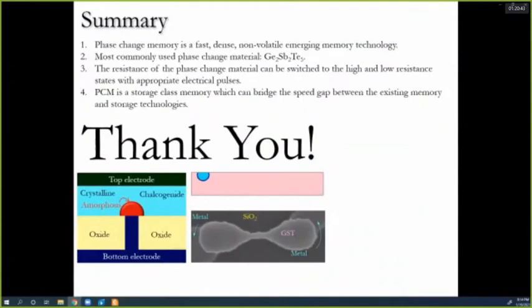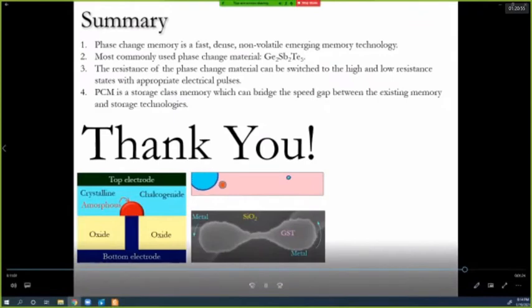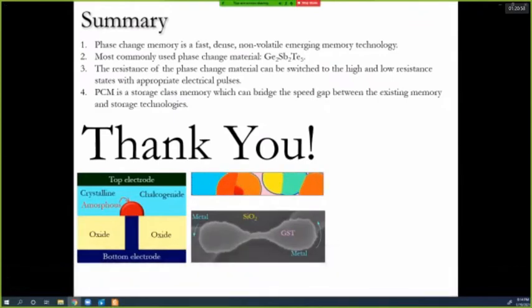I'd like to conclude this module with some key points. First of all, phase change memory, or PCM, is a fast, dense, non-volatile memory technology. The most commonly used phase change material is germanium antimony telluride with the 2-to-5 composition. The resistance of the phase change material can be switched to the high and low resistance states with appropriate electrical pulses that are called reset and set pulses. And PCM is a storage class memory which can bridge the speed gap between the existing memory and storage technologies.